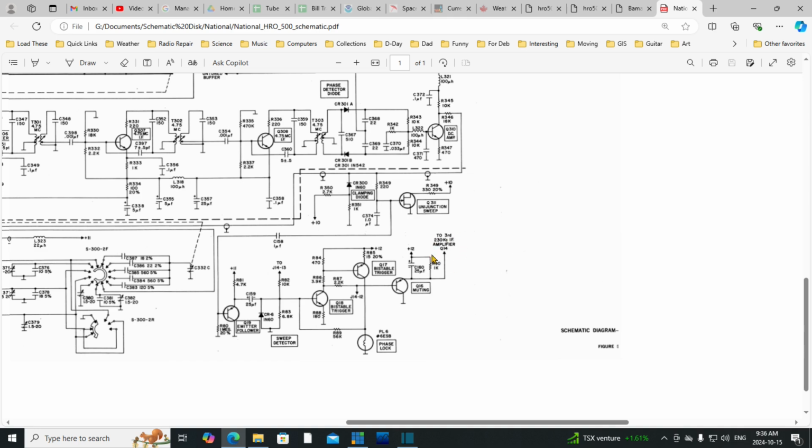I want to prove this is happening. Now, before I go directly on this, because these things are hard to access in the radio, they're a little dangerous too, trying to put leads in and catch places to make tests. Some of these voltages are presented on that big connector at the back of the radio. So here's one. The connector's number is J14, and this would be position 12 on that connector. Why, it's the base going right into this muting transistor. So we can look at the base voltage of this muting transistor, operate the radio, do stuff, and watch it go up and down or whatever.